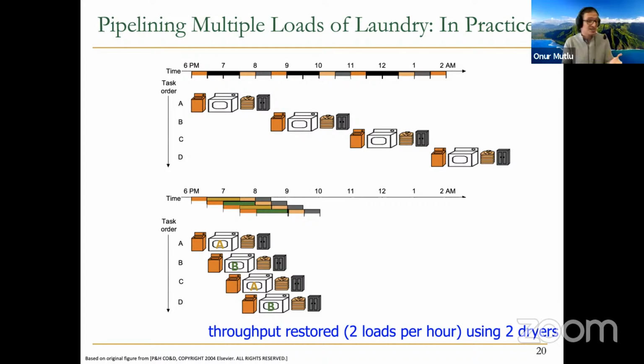We're going to see potentially similar issues in a pipeline. And this is called a resource dependence, or hardware dependence. We're going to cover it in more detail. Essentially, your pipeline throughput will be limited because different instructions at different processing stages may need the same resource. And if your resource cannot be made faster for some reason, you replicate the resource. And that's a fine solution to the problem. Of course, it adds hardware costs, as you can see, right?